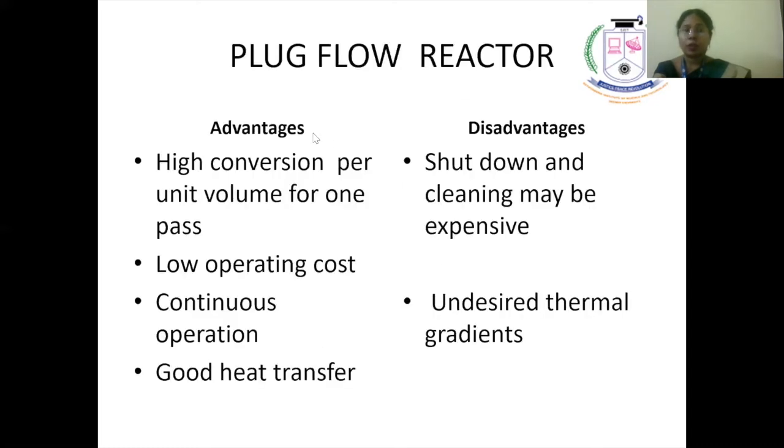So the advantages of plug flow reactors are high conversion per unit volume in one pass, low operating cost, continuous operation, and good heat transfer. The disadvantages are that shutdown and cleaning may be expensive, and there can be undesired thermal gradients.